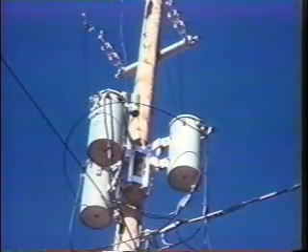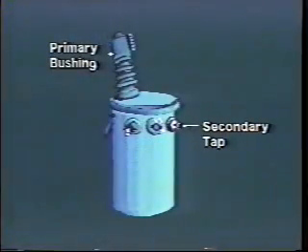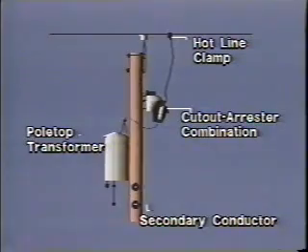Introduction of electrical apparatus into the distribution circuits adds a number of new components into the pole's bill of material. Most frequently, the apparatus will be clustered around a pole-top transformer used to step down the voltage from the primary to secondary voltages for customer service. In the simplest transformer tap, a hotline clamp, cutout and arrestor, transformer, transformer mounting bracket, and secondary connection assembly will be utilized.